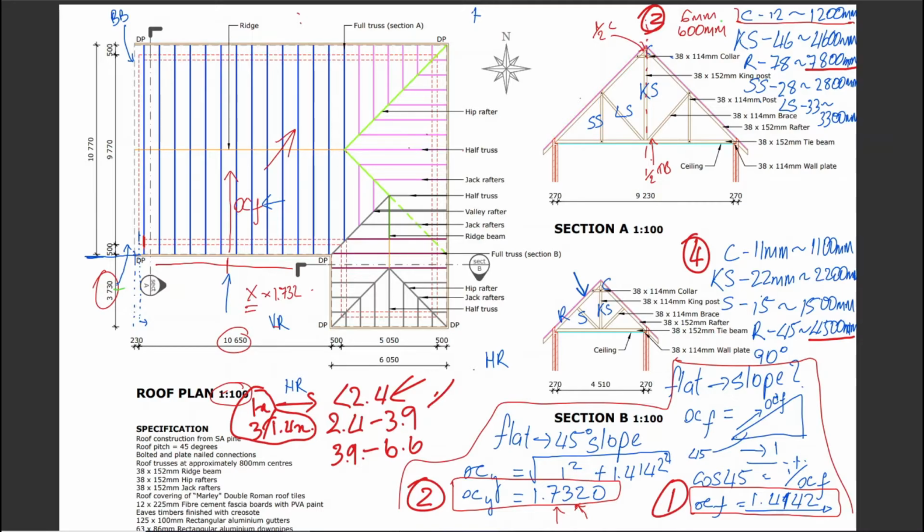So what I did was I just assumed it was, I think it's 345 again. And I said, well, 345 will fit into the 500. And remember, it's 345 on slope, so you actually have to consider that it's a bit shorter because it's on slope. So it definitely fits in. So what you'll say logically is that you can fit 2. And those 2, the first one would be your tilting fillet, and the second one would be your batten. And that is that.